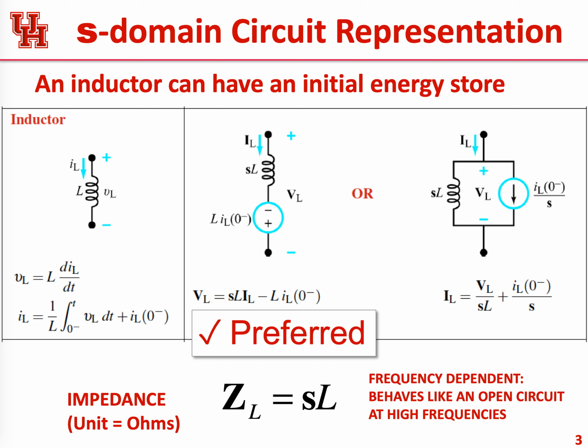So now if I were to take the same circuit and write that in the Laplace domain, then I can basically write a diagram that looks like this, and this diagram reflects this equation. Everything here is in the Laplace domain. So the inductance here, which was L, gets replaced with sL, which is this guy here. In series with that is this negative voltage, so we put a negative sign this way.